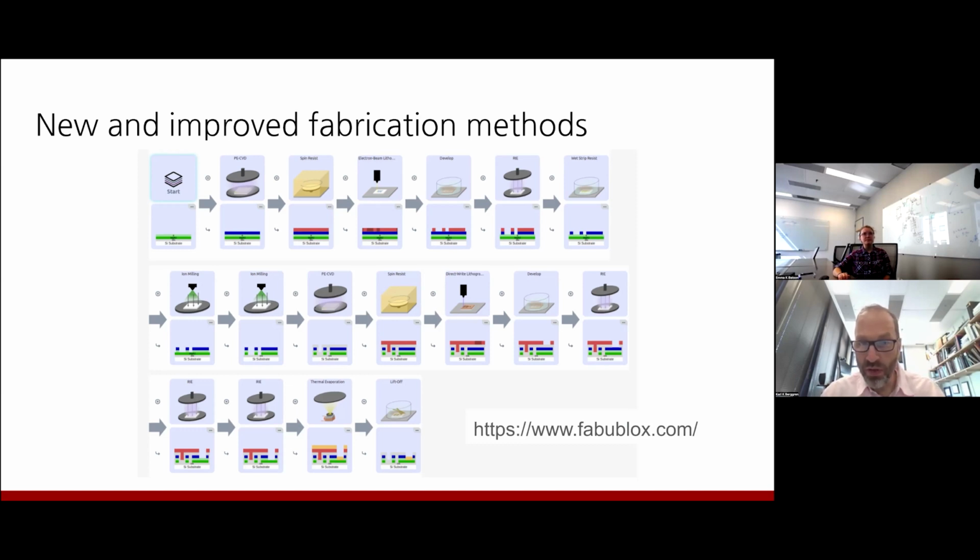We have a question from Shubhankar Hussain, who says, in the magnetron sputtering fabrication process, there was also a boron layer on top of the magnesium diboride layer. What is the purpose of that? Yeah, so this actually is a result of the way that the group at JPL does magnetron sputtering.